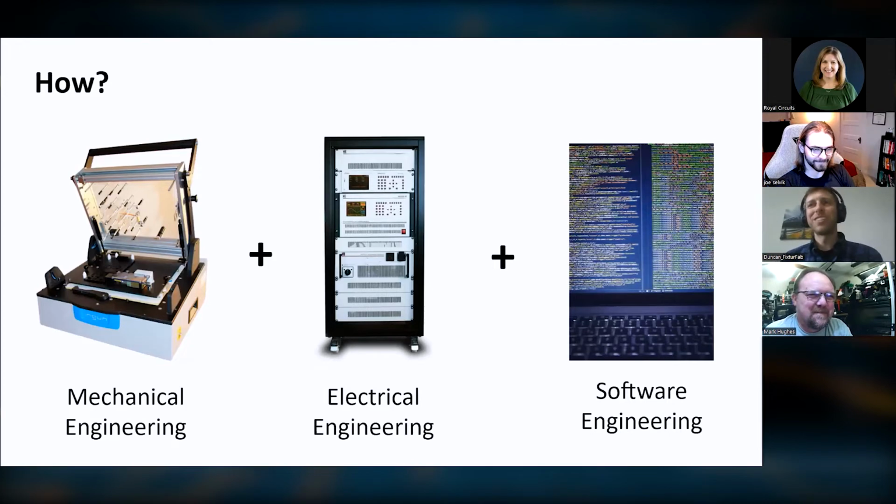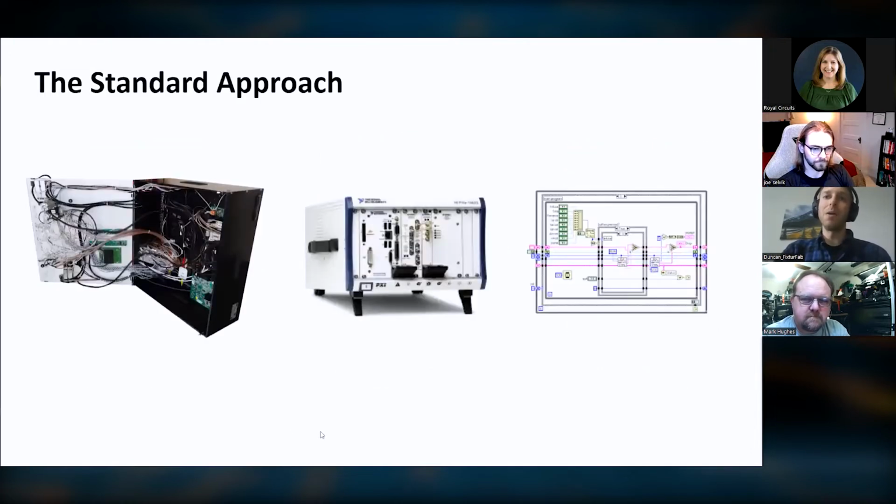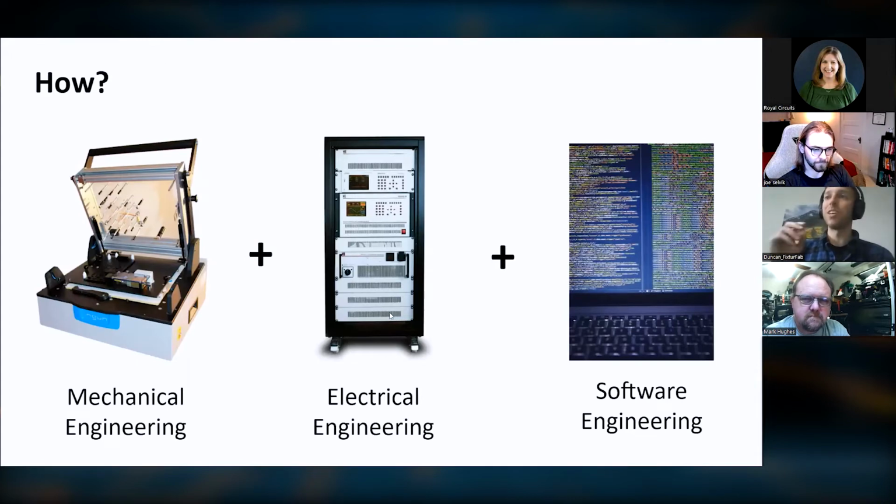Yeah. So to do this testing, you touch a bunch of different areas of engineering. And this is what actually got me interested in functional test engineering in the first place. You have a bunch of mechanical engineering that goes into designing a robust, repeatable jig that can mate with a circuit board over hundreds of thousands, if not millions of cycles during mass manufacturing. To do all the measurements and interface everything, there's a decent amount of electrical engineering involved, selecting the instruments that will be used to program or take measurements from the device that's being tested.